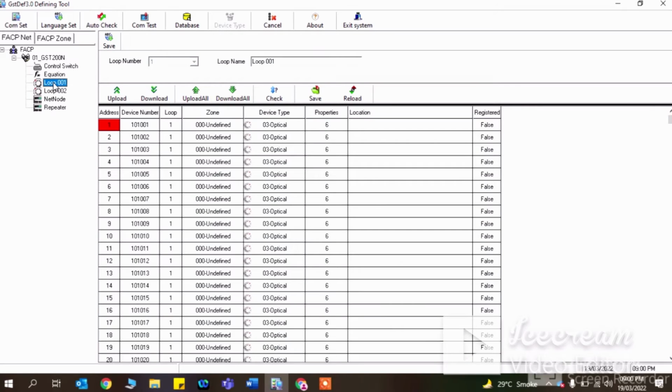So before doing all these things, first you need to check whether my panel is communicating with the device software or not, at a second level. Because sometimes your communication test will give okay, but here it may give some trouble. So to test that, what you need to do: for example, in my case I had connected 6 devices, address 1 to 6, connected here.